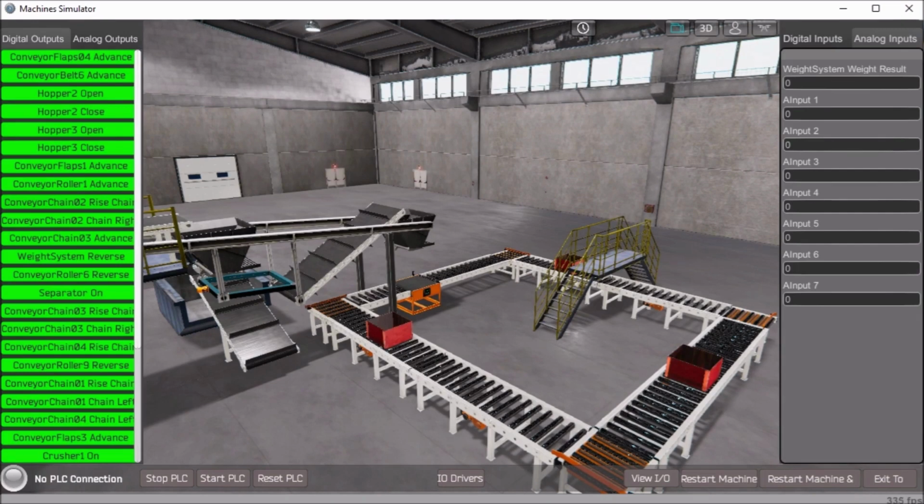If the box is detected on conveyor chain 2 and the weigh scale sensor does not have a box or is full, then the box can raise chain 2, then chain 2 is risen. We can run the chain left, and then the conveyor and waste station can then move along. So we want to take each box and rotate them clockwise and make sure that we're fully loaded on each one. So we do that for each of these corner boxes.